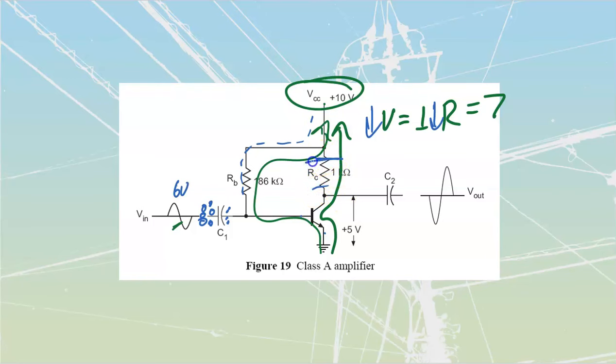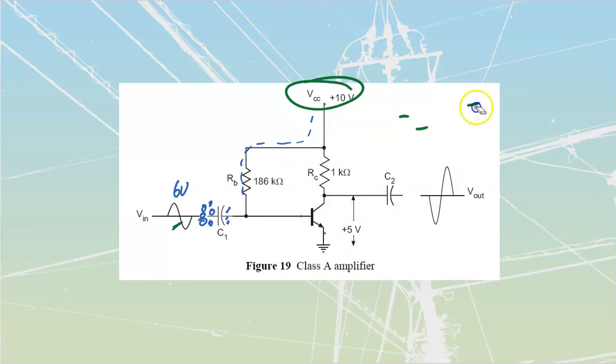Well, if this voltage goes down, this was dropping 5 volts over here, this now turns to 3 volts, that would mean that we would have to be doing the makeup down here, 7 volts that we would have across here. And so I'm going to see an inverted waveform out there. That's the way that we take our signals, we pass them through.